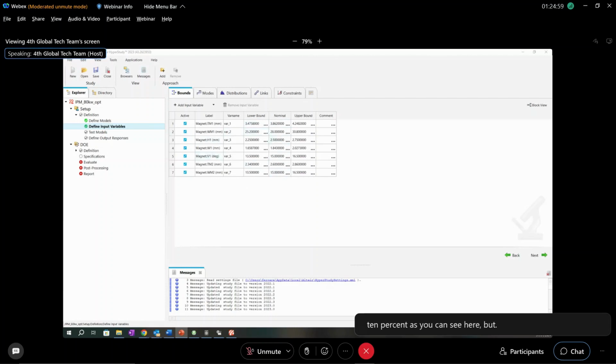But we need to do some changes to avoid intersection and errors in the geometries. It is quite difficult to do this process since, depending on the variation of some parameters, we can find intersections very easily. So it's a process that we need to think about before starting the optimization. To do that, we can open a FluxMotor model to be able to change the parameters.